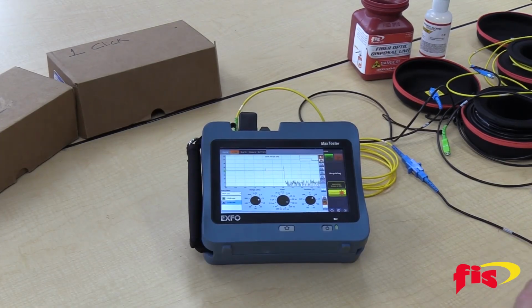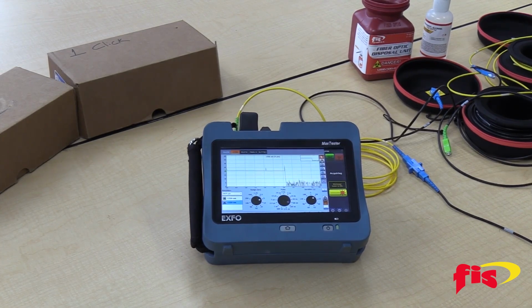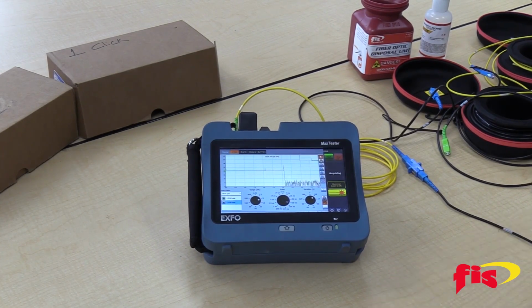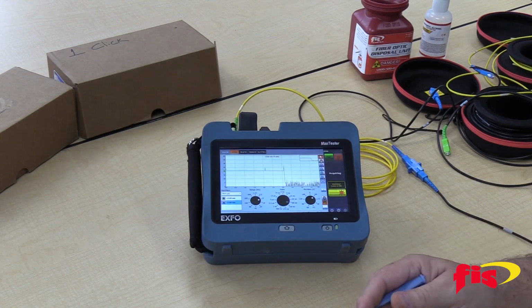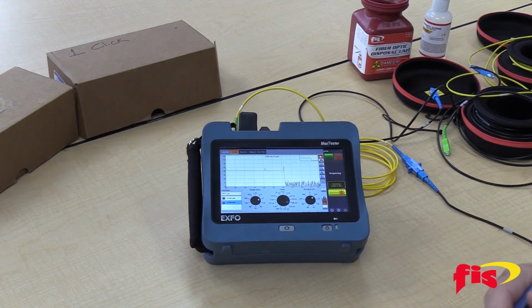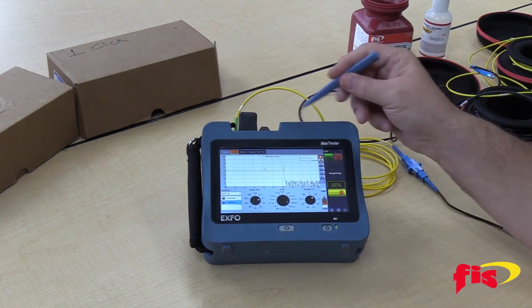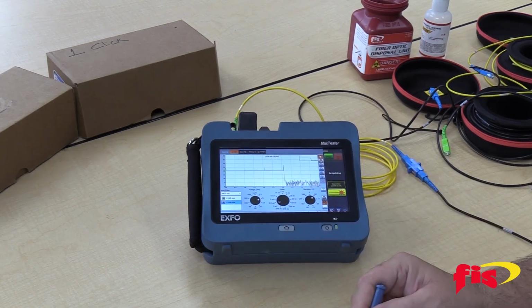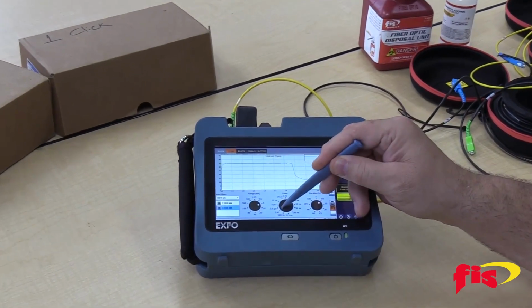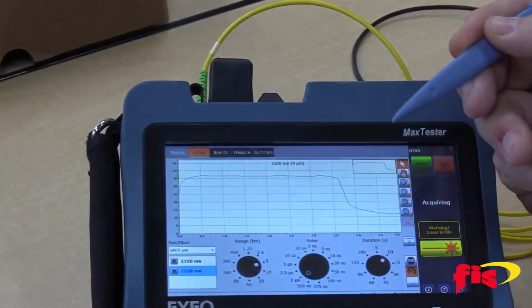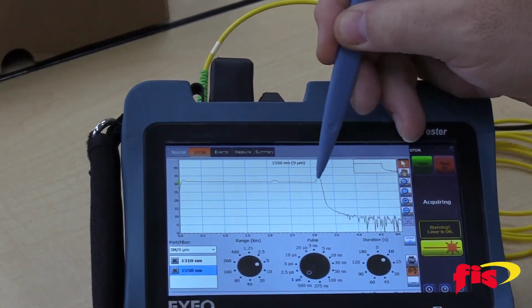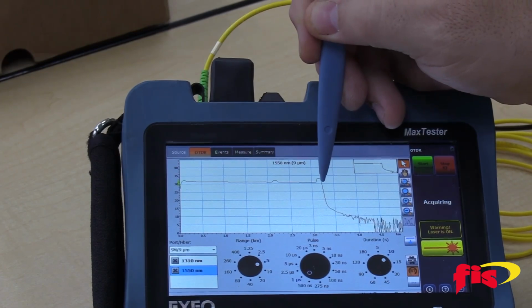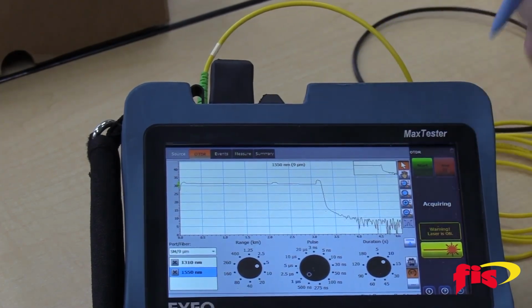Now, why do I do that? A couple of reasons. Your dead zones, the area of distance you lose after every connector, grow depending on the pulse that you use. The longer the pulse, the longer the dead zones. I'm showing you this here in real time because, look, I'm going to turn that pulse way up. Look at your dead zones. Oof, that's a little more than we need. It's a lot more than we need. You can see how much wider these are becoming. So the longer the pulse, the longer the dead zones.